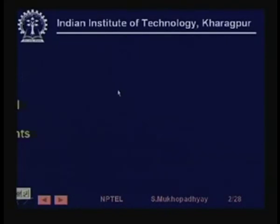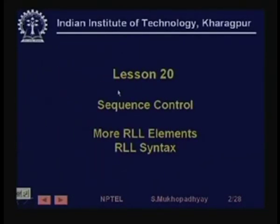Welcome to today's lesson, which is lesson number 20 of the course on industrial automation and control. Today we are going to look at some new programming elements, namely timers, counters, etc., which are required for RLL programming. We are going to understand their meanings and see their use in real simple but real typical industrial programs.